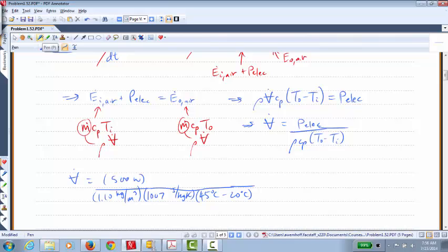When you have a temperature difference, it turns out that since degree C and Kelvin have the same magnitude when you look at a difference in temperature, right? So again, a Kelvin is a degree C plus 273.15 degrees. So what we can say, because we have a temperature difference, is replace the degree C with a Kelvin.